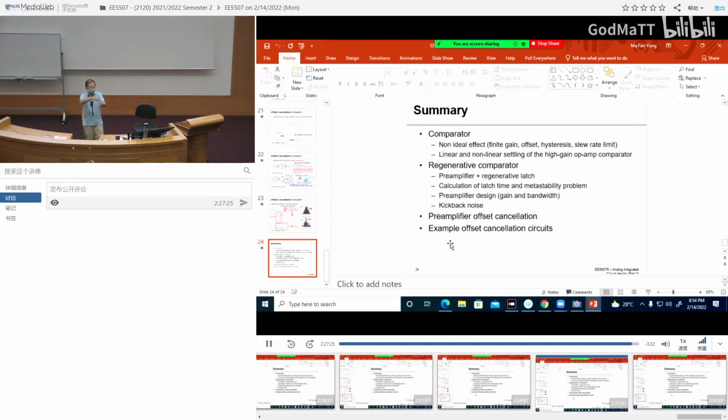Draw the schematic, connect all the wires. When you finish everything, generate a netlist. A netlist is just a description of your circuit, and then run the simulation. That means define what your stimulus is, what your voltage is, and then define what waveform you want to see, what analysis you want to do, small signal, transient, or DC, and then how to see the output.